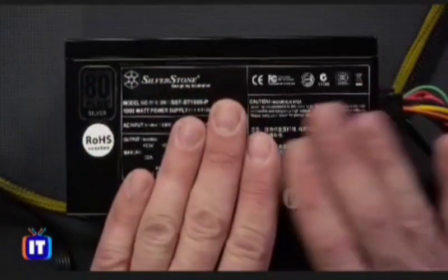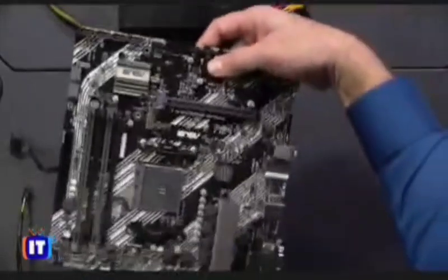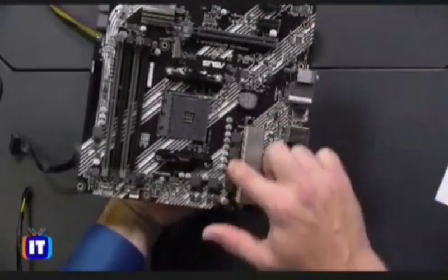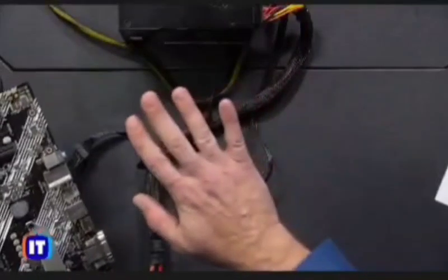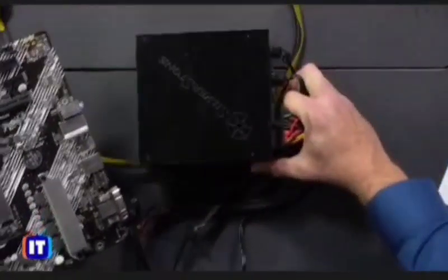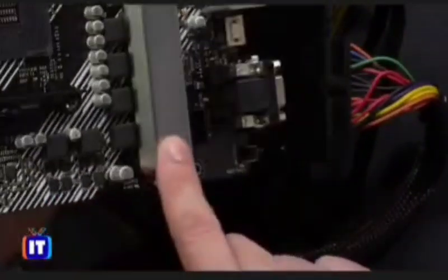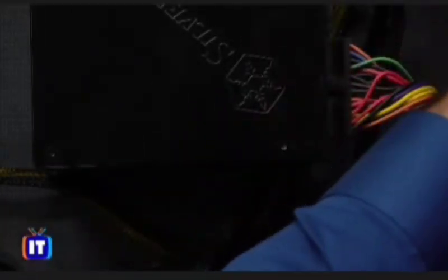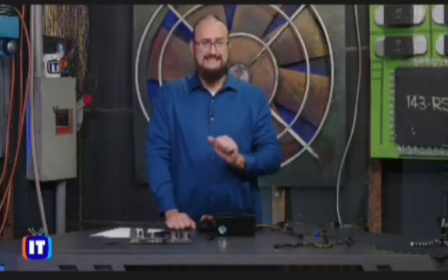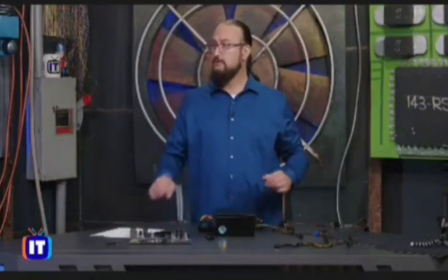So what your power supply is doing in combination, and let me bring our motherboard over here, in combination with these voltage regulator modules that are built into the motherboard, is it actually steps the voltages down to the appropriate levels for what we need to power our computer circuitry, right? And you can see a series of capacitors right here, and that's all part of a voltage regulation module that happens inside of your power supplies. So it is important. Remember, converting AC to DC and then doing voltage regulation and stepping those voltages down to the 3.3, the 5 volts, and the 12 volts that our components operate on.